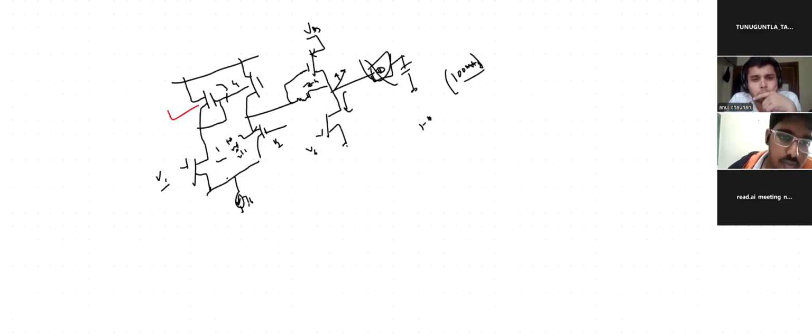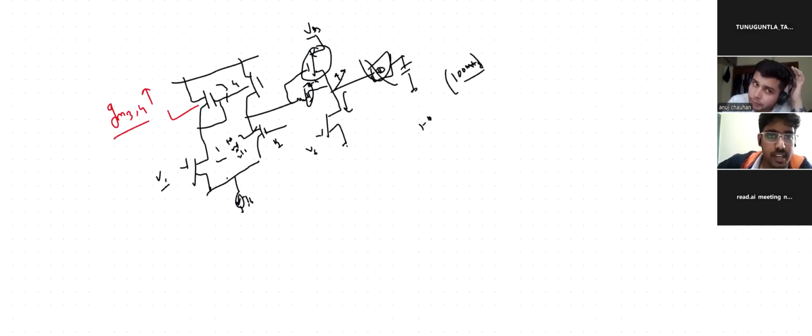From the knowledge I got from the circuit, the gm of 3 and 4 and this gm are dependent, sir. In this circuit, this capacitor plays a very important role. If I keep gm of 3 and 4 high, then what is the problem? If the gm of 3 and 4 is very high, say if I keep it 10 times higher than what we have used presently, then what problems can be expected in your circuit?